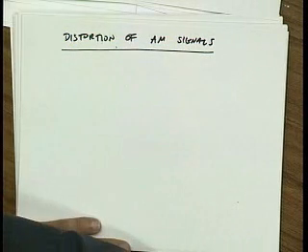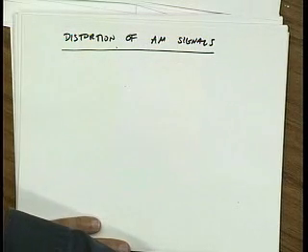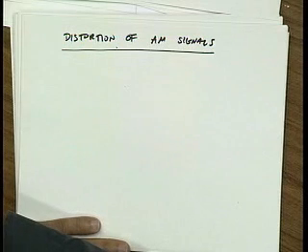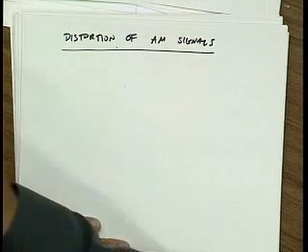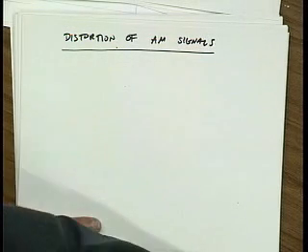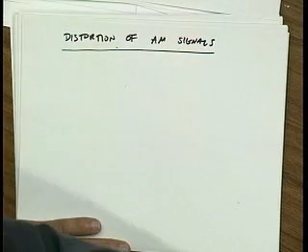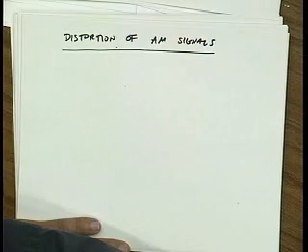It's also used for video. The video you're watching, it's very inefficient, but it's amplitude modulation. The reason it's amplitude modulation is that amplitude modulation is more spectrally efficient than phase modulation or frequency modulation. So even though on televisions we'd like to use FM, that would use up too much spectrum. So we use AM for the video and we use FM for the audio. So the audio is actually sent through FM, but the video is amplitude modulation.